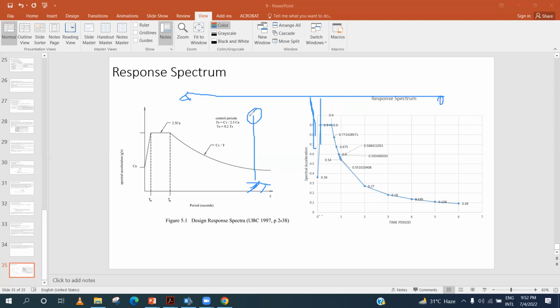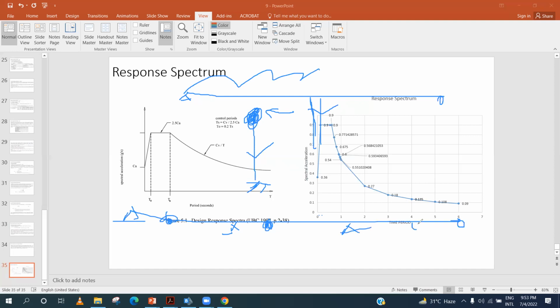in which the whole mass can be concentrated at one point and the force can be applied, and the stiffness of this column is the stiffness of the substructure or the overall bridge. But in the multi-mode response spectrum, we divide the mass of the bridge into multiple concentrated masses and then subject it to ground motion.